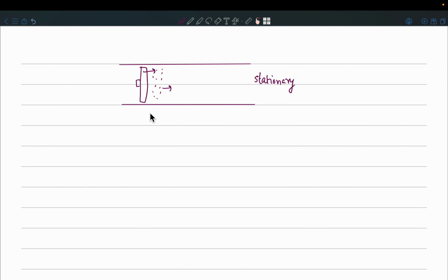So you have introduced a perturbation to the flow over here, and that perturbation is going to be carried forward. Understand that the perturbation in a fluid is not carried just by one particle's motion. This particle will push another particle, that will push another particle, and so on, and the perturbation itself will move with the speed of sound, right? So a wave front is going to be created, and this wave front is going to move forward with some speed c, and the piston itself you had perturbed and moved it with some speed v.